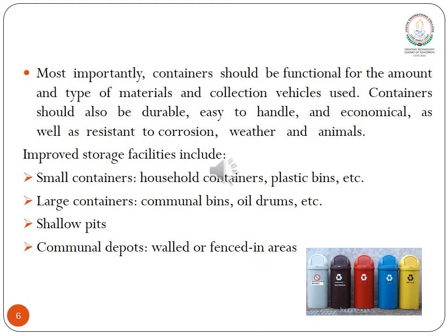All solid waste must be stored in fly-tight, watertight, rodent-proof containers or in other suitable containers with secure lids. The containers must be located not more than 300 feet from any trailer space or campsite. Containers must be provided in sufficient number and capacity to properly store all solid waste between the collections.